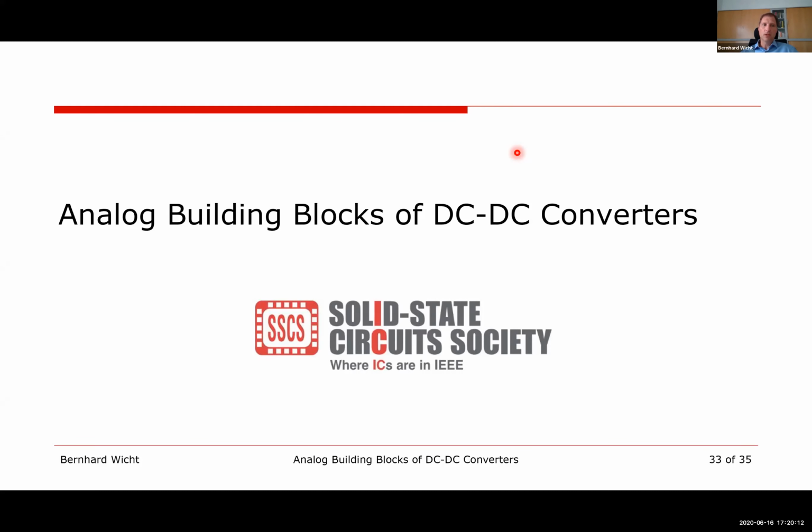And in terms of reliability testing, of course, all these techniques like we have seen, like the thermal shutdown or the thermal circuit, need to operate at much higher temperatures compared to the regular operating temperature. So in back-end of line testing of the IC, you usually don't want to go to 200 degrees. That's something that's verified at bench level.